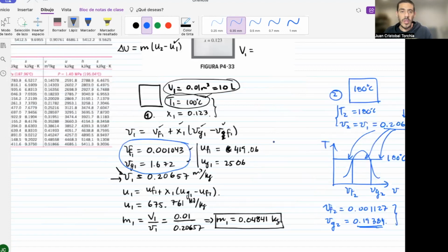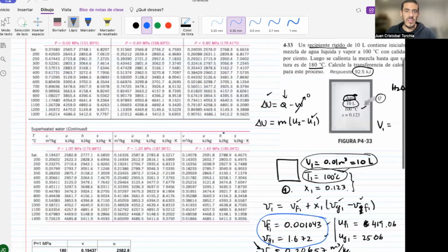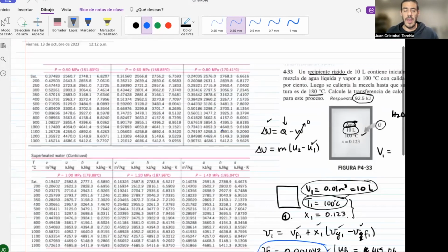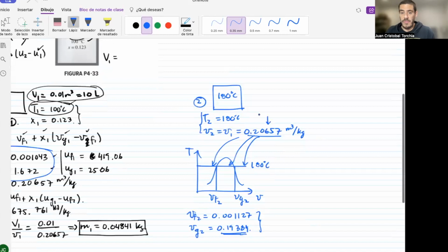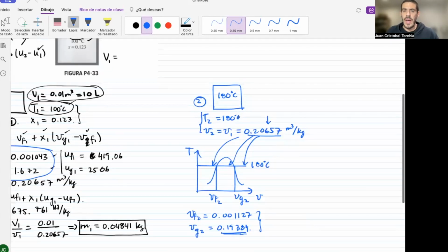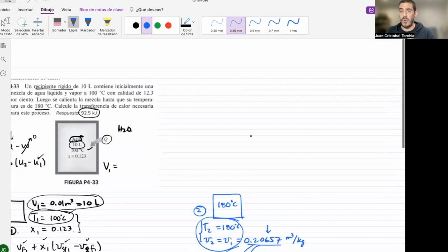So that's what I have put here. So these are my superheated steam tables, okay? And maybe you can see now the problem. If I somehow knew the pressure, I could go into those tables, but I do not have the pressure. I just have temperature and specific volume. So my first way to do this problem is by an approximation. Okay, so I'm gonna put it here. This approximation